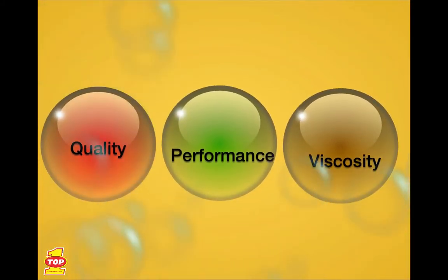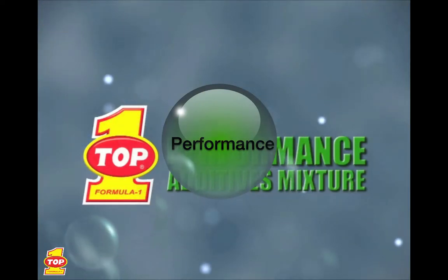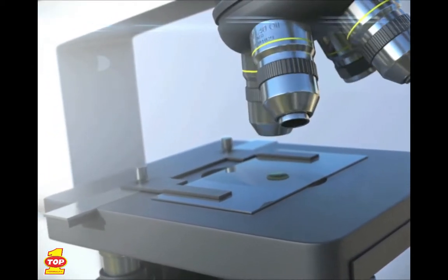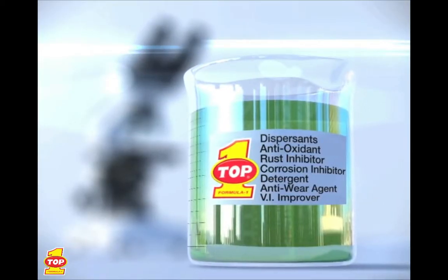Performance. Specialty chemicals called additives define the performance of a finished lubricant. Types of additives typically used in motor oils include dispersants, antioxidant, rust inhibitor, corrosion inhibitor, detergents, anti-wear agent, and viscosity improver.